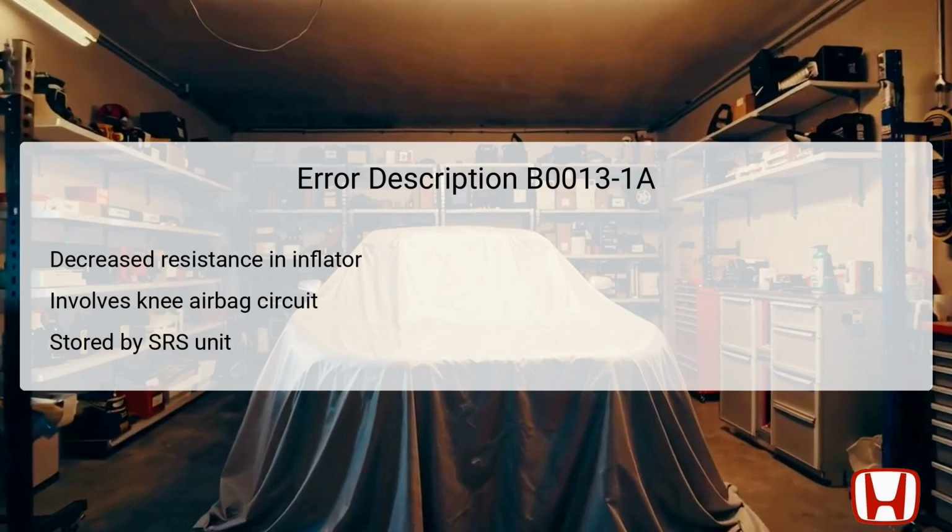The DTC B0013-1A indicates a decreased resistance problem specifically in the front passenger's knee airbag inflator. The front passenger's knee airbag is designed to protect the knees of an occupant during frontal impacts by deploying quickly in a collision. If the SRS unit detects that the resistance on the detection line is lower than a predefined value, it signals an issue, prompting the storage of this DTC.